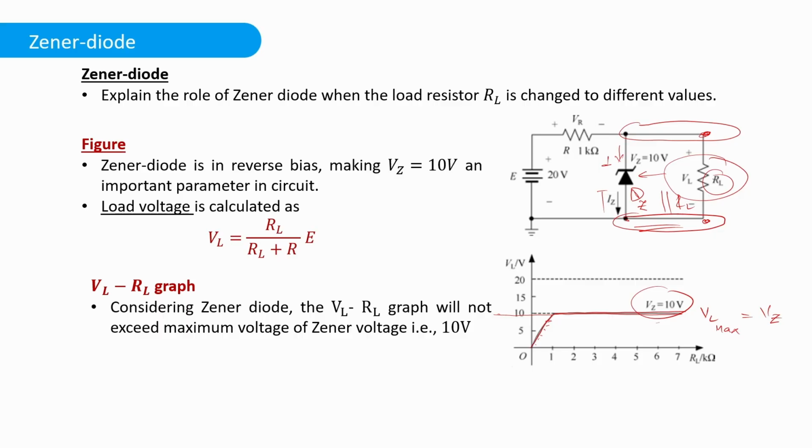Once again, just to explain it to you, Zener diode over here and this load voltage. Let's write it over here. Zener diode and load, they will be in parallel with each other. So once they are parallel with each other, what happens is that the Zener voltage will be equal to load voltage. No matter how much input source we apply to it, this will never cross that because they are in parallel. And we know that in parallel, voltage will always be same.